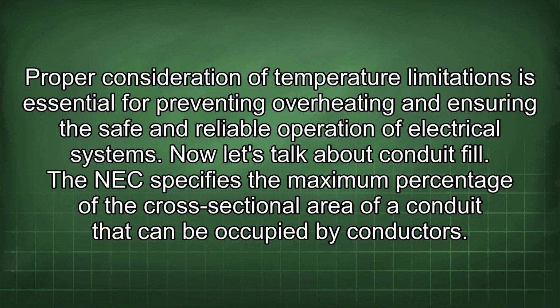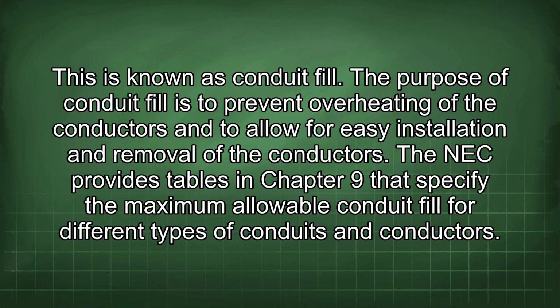Proper consideration of temperature limitations is essential for preventing overheating and ensuring the safe and reliable operation of electrical systems. Now let's talk about conduit fill. The NEC specifies the maximum percentage of the cross-sectional area of a conduit that can be occupied by conductors. This is known as conduit fill.